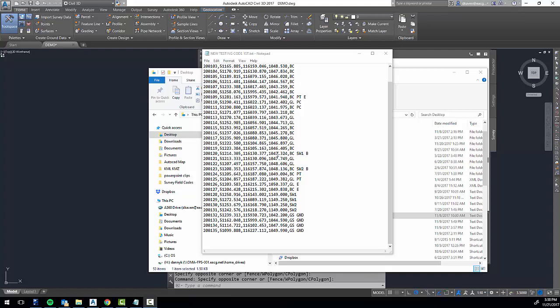At this point, you can see here that we've got some back of curb, and then we have a space. And then we're defining it yet one more time. So we got 1 point, and it's got 2 codes basically. So we're telling it it's back of curb, and then we're going to begin a sidewalk there. Go back to the gutter line, and then we've got sidewalk 2 there.